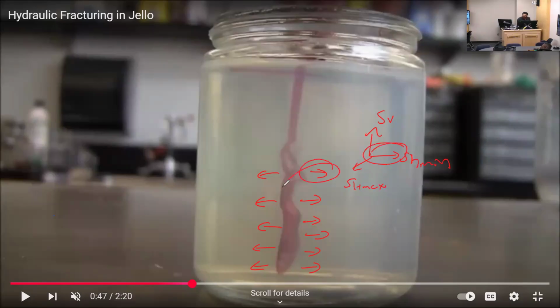So you see this is in the same direction as these stresses, right? How you are opening, it's the width of the fracture that matters. The thickness, not the width of the fracture, the thickness, how it opens, the smallest dimension. Okay, if this is the fracture, all that matters is this. The direction that this is on, in this case, is this direction. This is my direction of the smallest of the stresses.